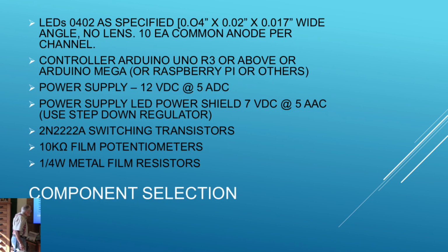LEDs 0402 are specified. They're, I'm sorry, inches. I thought millimeters. They're not. They're inches. No, that's millimeters. At any rate, yeah, they're millimeters. I made a mistake. It's not inches. They're wide angle, no lens. All right, and there's 10 of them per channel.